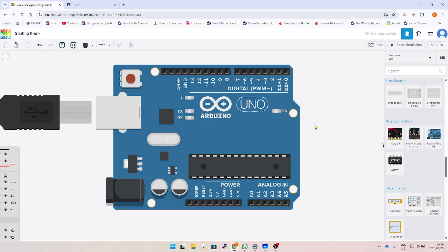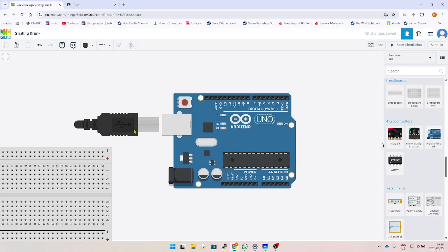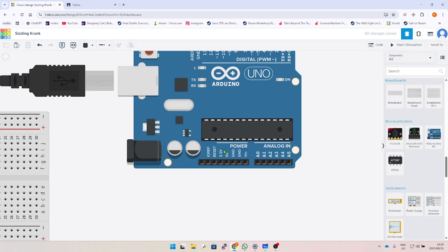In circuit serial programming. What this means is instead of plugging in this board here with this USB cable, I can attach a few pins here and control this microcontroller directly instead of programming with your Arduino IDE. That's all you need to know in this case. So it's for direct programming.